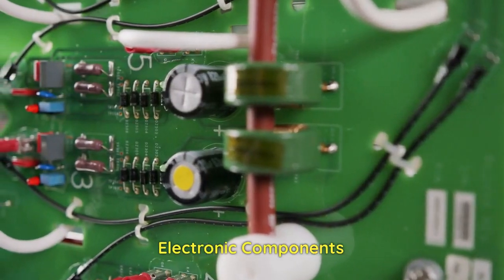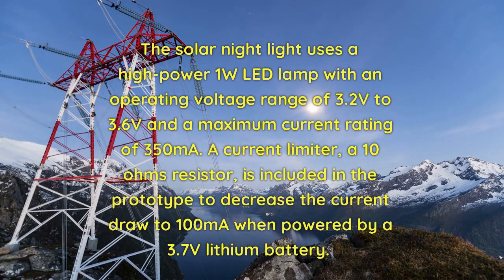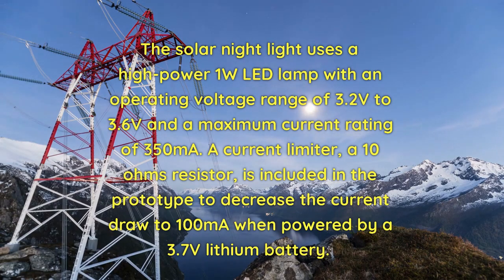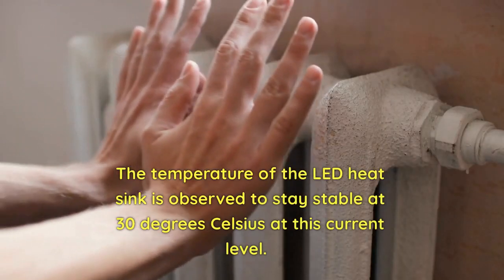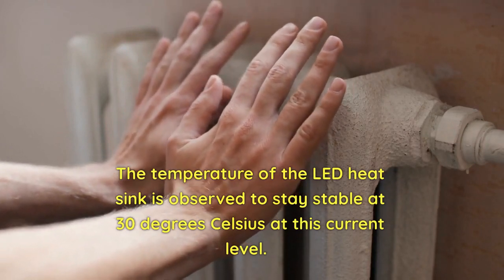Electronic components. LED lamp. The solar night light uses a high-power 1-watt LED lamp with an operating voltage range of 3.2 V to 3.6 V and a maximum current rating of 350 mA. A current limiter, a 10 ohm resistor, is included in the prototype to decrease the current draw to 100 mA when powered by a 3.7 V lithium battery. The temperature of the LED heatsink is observed to stay stable at 30 degrees Celsius at this current level.